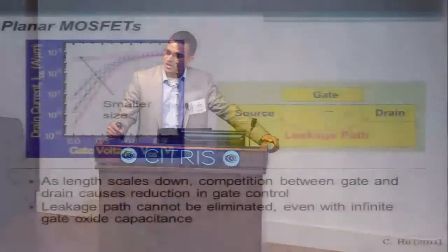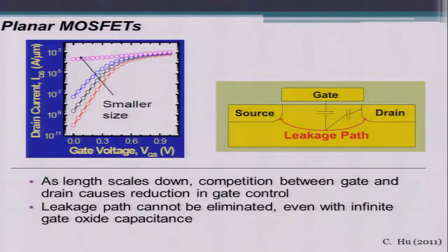I thought the previous talk, Sapan did a great job of talking about the various constraints that you have to think about when designing your tunnel transistor. I'm going to add one more constraint, and that's the scaling law. We cannot forget about the scaling of transistors, and all of you are familiar with this. As you scale your devices smaller and smaller, if you grab a planar MOSFET, you go from a switch to a resistor. So you have severe short channel effects.